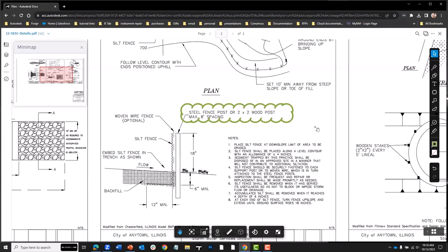When we create markups, those markups can be saved in two ways, published or unpublished. A published markup is viewable by anybody that views this file. An unpublished markup is only viewable by the creator. So you can use the feature to create notes to yourself if you wanted to. If I click to select this markup, from right here, I could publish this so it could be seen by others. Before I do that, just take a look at some of the other options that are available in this menu. I'm going to choose Publish for right now, and then I'll click on Screen.